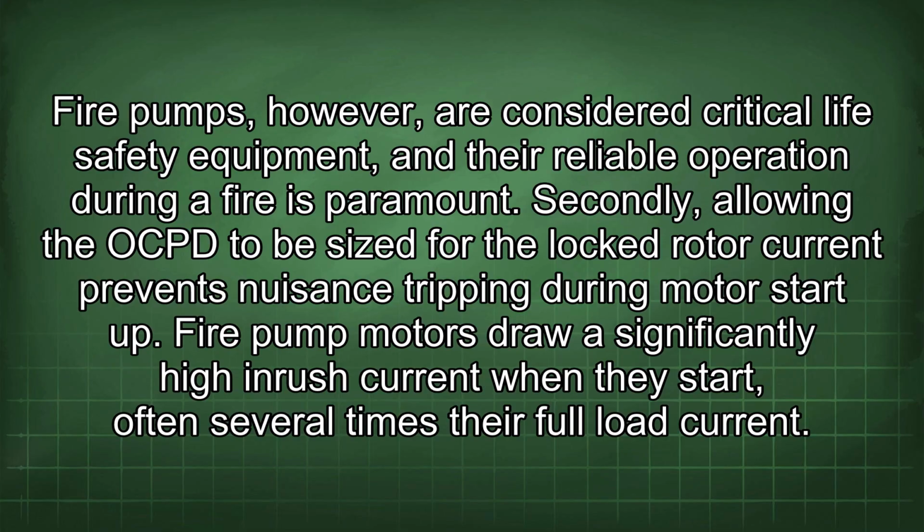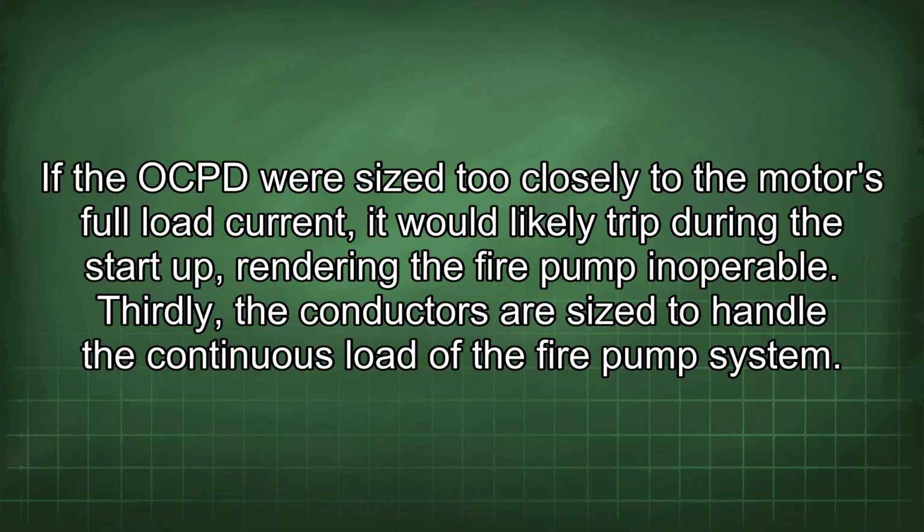Secondly, allowing the OCPD to be sized for the locked rotor current prevents nuisance tripping during motor startup. Fire pump motors draw a significantly high inrush current when they start, often several times their full load current. If the OCPD were sized too closely to the motor's full load current, it would likely trip during startup, rendering the fire pump inoperable.